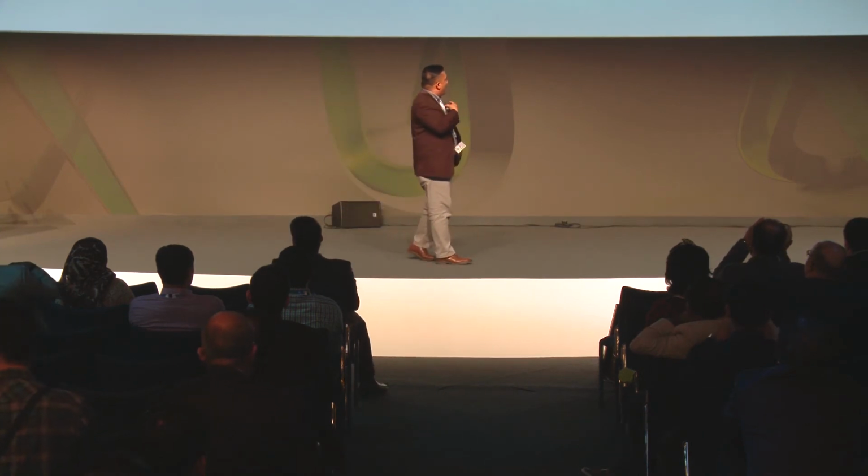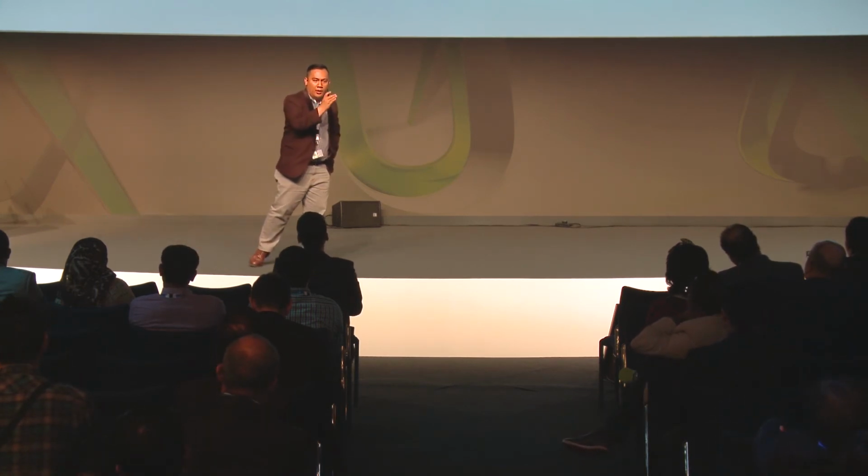a post-contract BEP. Now in this post-contract BEP, what I normally check as a BIM manager is the workflow and processes in terms of the creation and management of the required information. If the contractor did comply with the management and practices to fulfill the information requirements, then I have to chop this BEP, and then I can say, okay, you can start your modeling. If the contractor hasn't fulfilled the requirements of the post-contract BEP, I won't allow them to create the model, because at the end of the day, that model is useless because it doesn't comply with the requirements of the client.